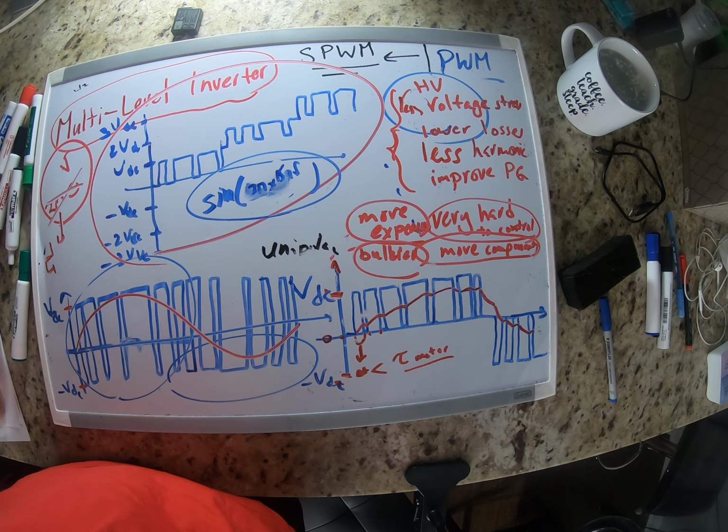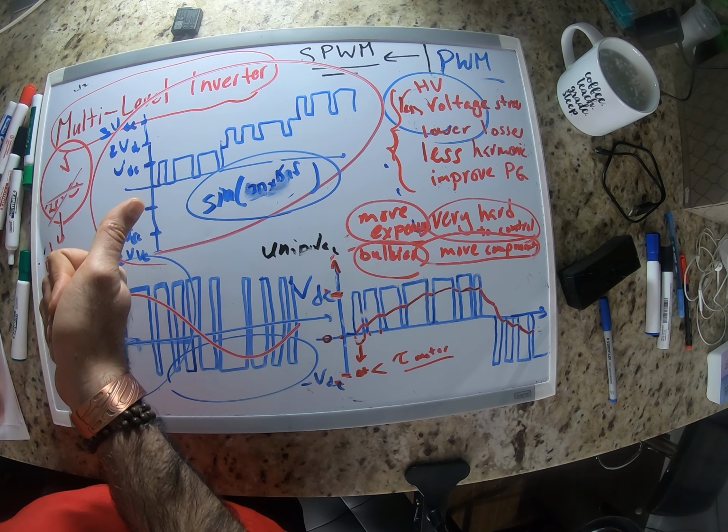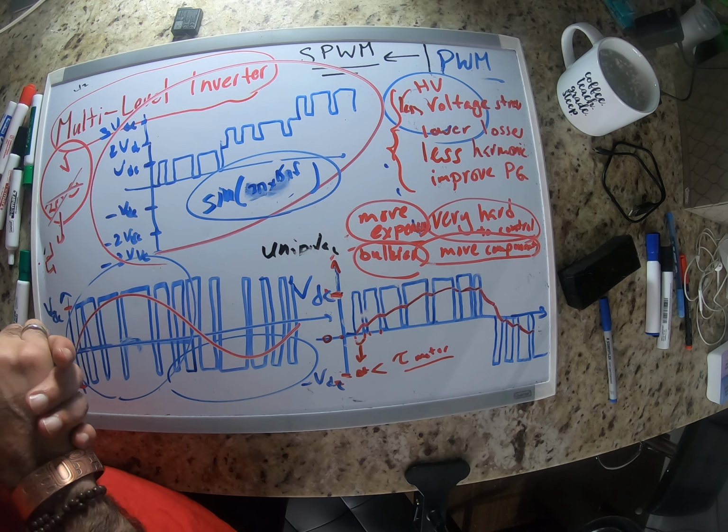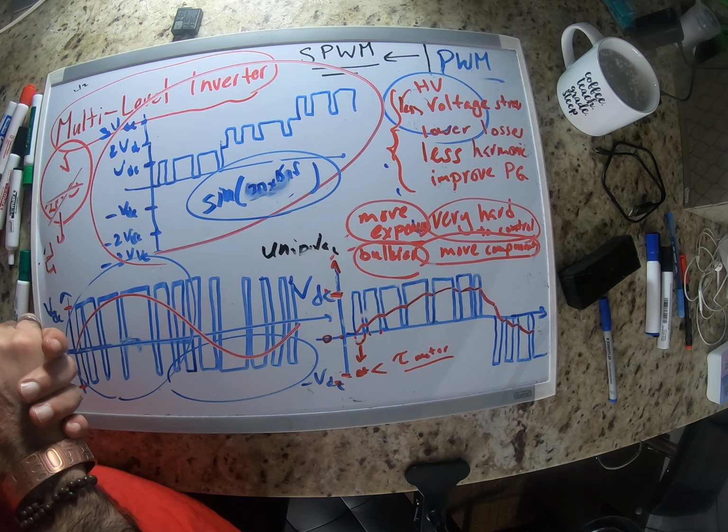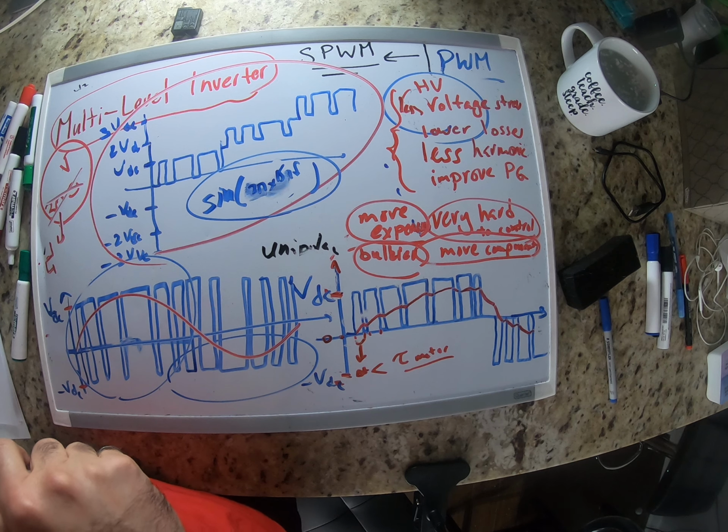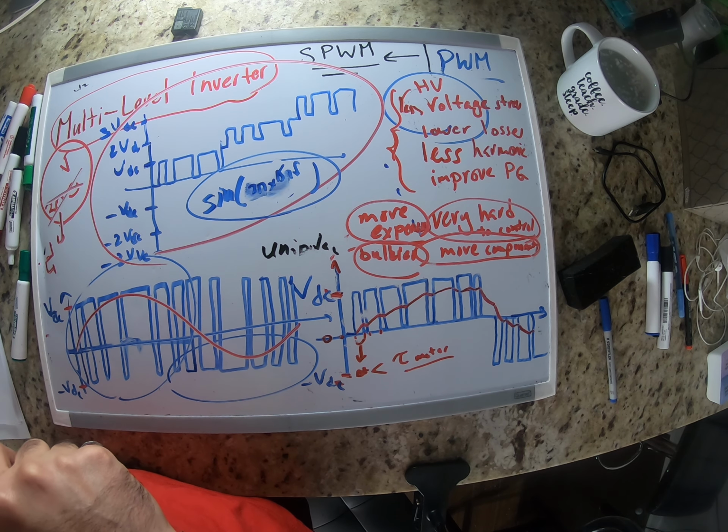One other thing I should mention, usually the switches are very expensive and are very sensitive, right? So that's why we have a lot of protection in practice. We have a lot of protection for switches as well, because we want to save them from spikes, from accidental triggering, from errors in the program, like the PWM program. So there are going to be a lot of protection, like fuses in the circuit, that we are ignoring here. We are simplifying the circuits here. So that's what I wanted you to know.